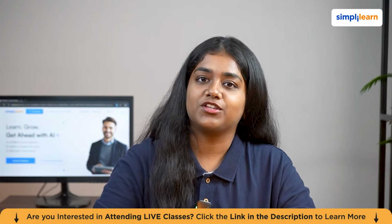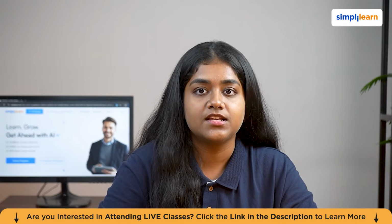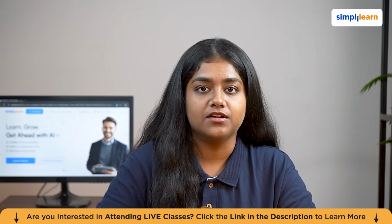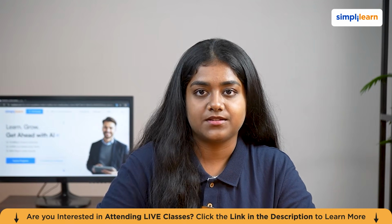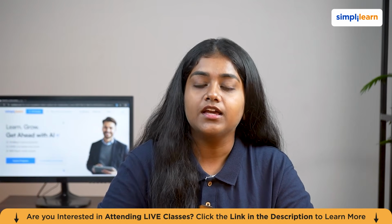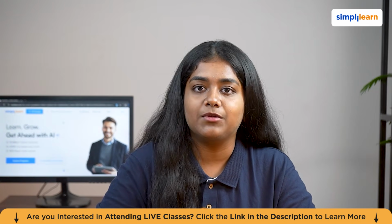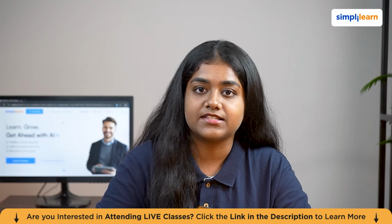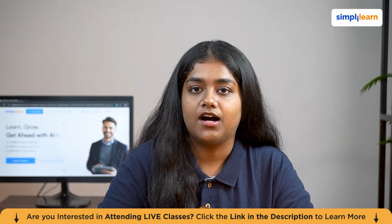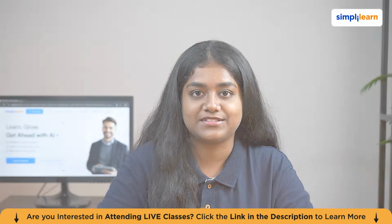So with this, we have come to the end of this module. In this module, we covered the foundations of what a measurement system is. It's not just the instrument, but the complete combination of equipment, operators, method, environment, and parts. We explored how data quality depends on both accuracy and reliability, and how poor measurement systems lead to flawed product decisions, unreliable process control, and misleading capability studies. We also had a look at the critical concepts of bias, variability, accuracy, precision, and the impact of gauge error on hypothesis testing decisions.